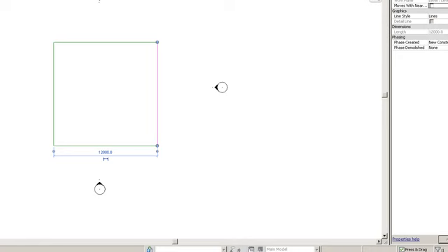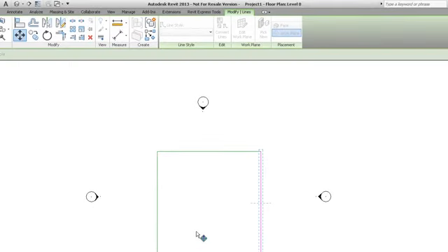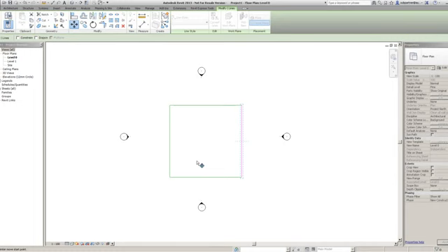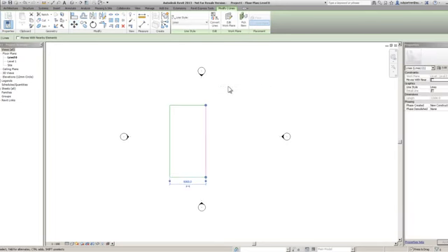We have the move command. Now the move command is basically exactly the same as the move command within AutoCAD. I'm going to take the move command, because I've highlighted the object first and gone move, the object that I selected is now what we're moving. It is our pre-selected object and we are just going to be moving it. Just like with AutoCAD, all we do is pick a base point. We can pick it off of the object if we want, because the distance between them always remains relative. I'm just going to move my mouse in that direction. Let's just say I want to move it across there, 6 meters, 6, enter. What it's done is just moved that line across 6 meters, nice and easy.